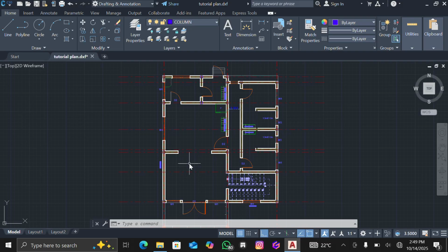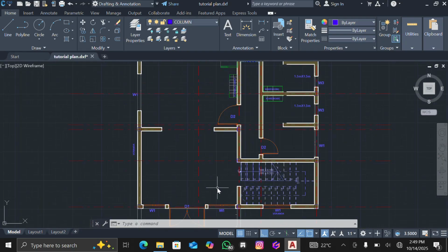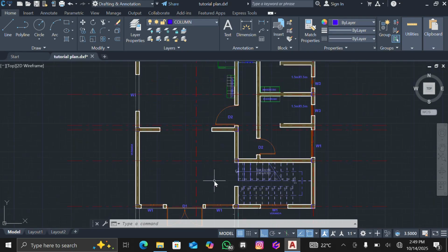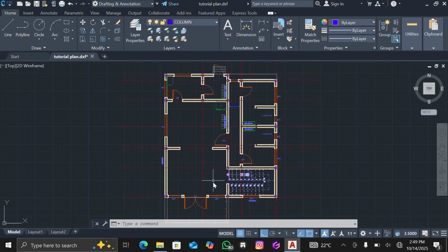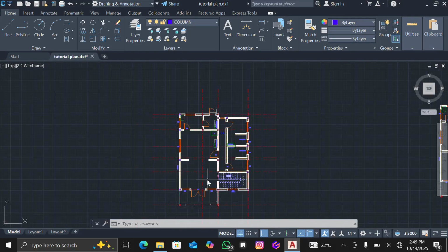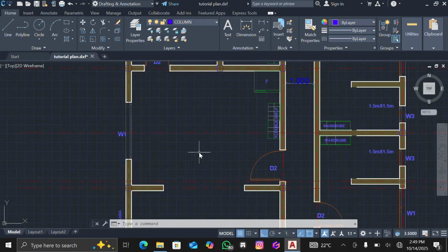You can take an example when someone is up on the building and then maybe they throw something on the floor. In case you hear that floor vibrate, it means that there's something not right with that panel. And one of the reasons why it can vibrate is when the panel is very much bigger than 30 square meters. You understand? It can bring about that effect. There are also other things that can bring about that.